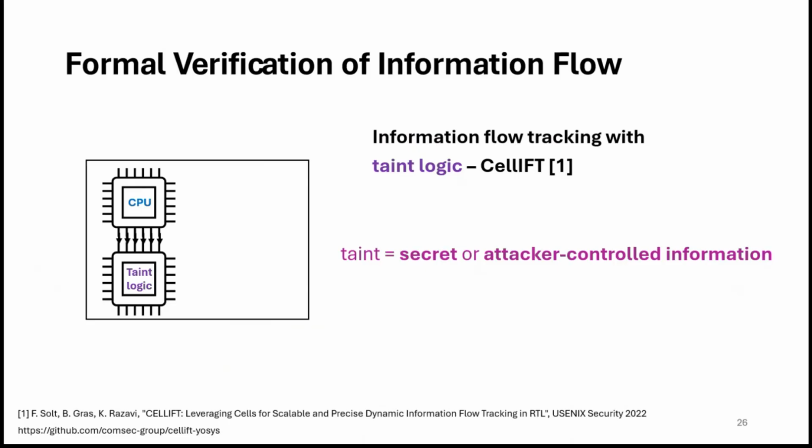For the verification of these IFT information flow properties, we use CellIFT, which is a taint tracking logic developed by my co-author Flavio Solt. It's open source. It's a logic that you take and augment the CPU with. So it is like a shadow logic that tracks how information flows through the design. And the taint represents either the secret or attacker-controlled data that we are interested to monitor.